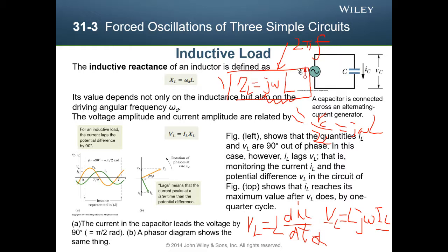But if we have many frequencies for the source, how will it work? You use the Fourier transform. You can transform it from the time domain to the frequency domain. Then you can distinguish different frequencies of the original signal, and then you multiply by the transfer function of the circuit, and you get the output. Because you have x of t, and you convolve it with the impulse response of the circuit. So you will get the output.